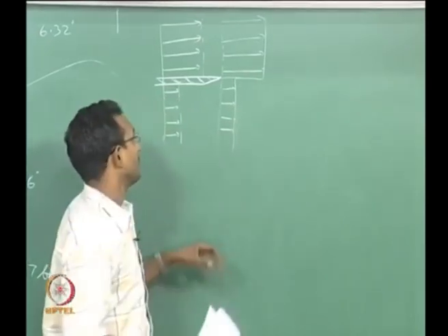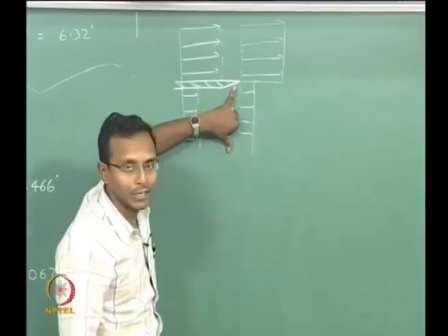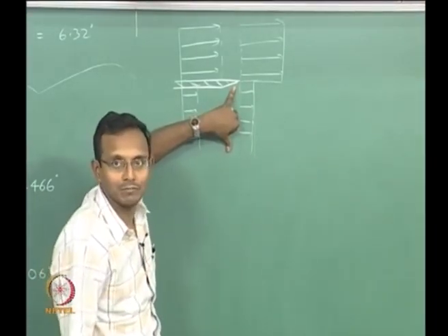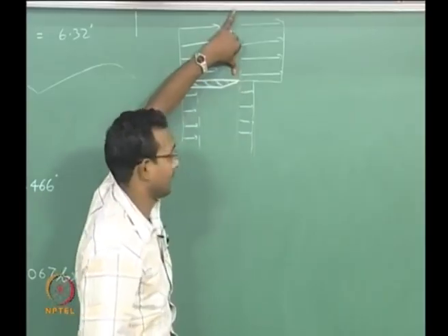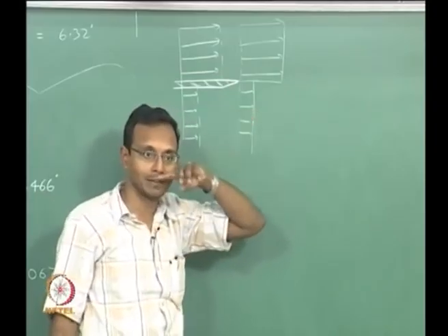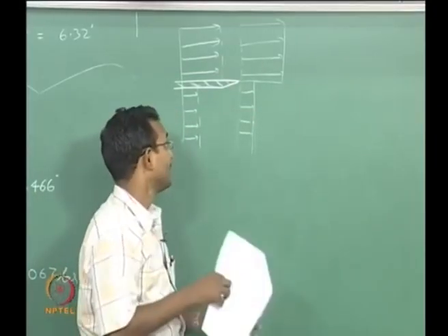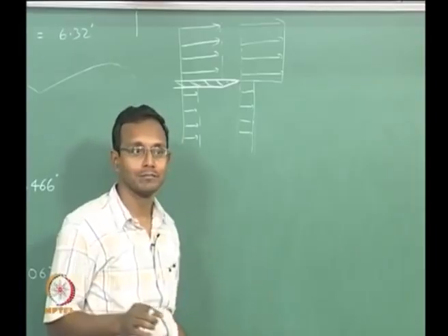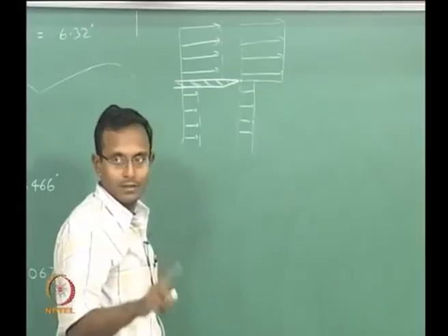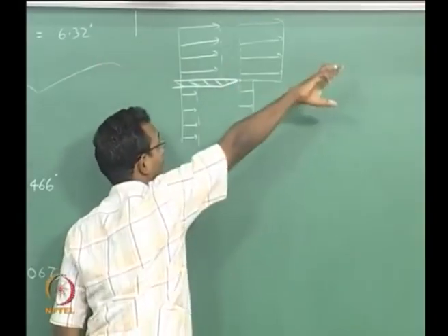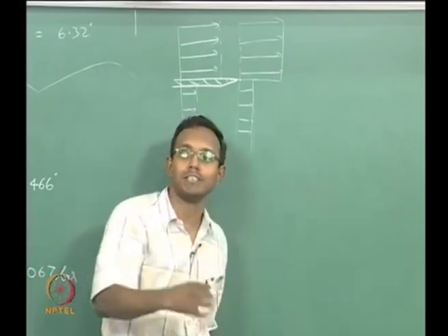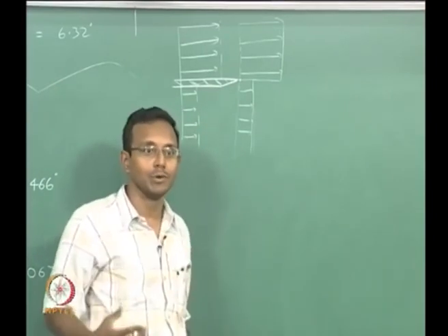If I think about vorticity in this region, there is no vorticity at all, because all the velocities are exactly the same and del cross V becomes 0. Same thing on that side, except for that one line, the center line, which will be the only region where you have non-zero del cross V. That is where the vorticity is distributed, and all the fluid elements are going that way, which means I am going to have overall some convection of this vorticity distribution as it goes that way.